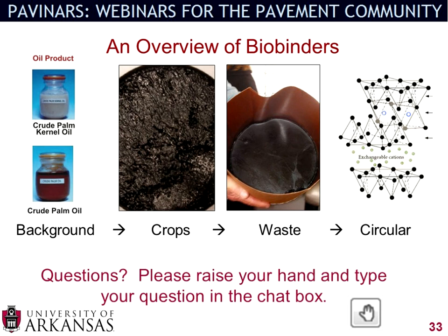Because there weren't any strong indications of the material degrading beyond what you typically see with asphalt cement, it's my opinion that we're not seeing a whole lot of degradation of the biobinders because they're biobinders. I think all materials degrade over time, and we're seeing some of that, but I don't think there's anything specifically with the biobinders that we need to be concerned with.